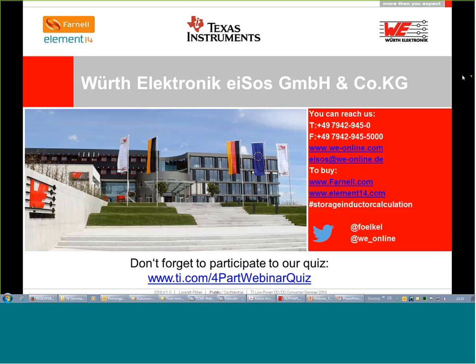I will definitely use in that case a transformer design. If you have that kind of high amplification, with such a small current, a small flyback would also fit, but the inductance will be quite difficult. It would work, yes, with a high millihenry inductance maybe sometimes. It depends also on the switching frequency, of course. But I will definitely try a transformer flyback topology.